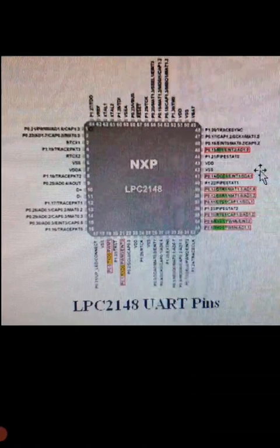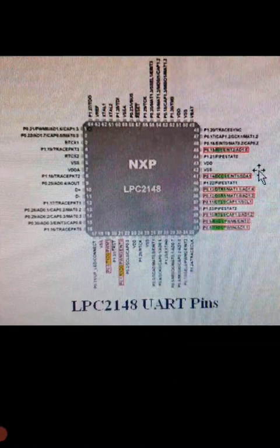In the UART0 registers, the first register is the UART0 receiver buffer register. It is an 8-bit read-only register. This register contains the received data. It contains the oldest received byte, and the receive FIFO is first in, first out.